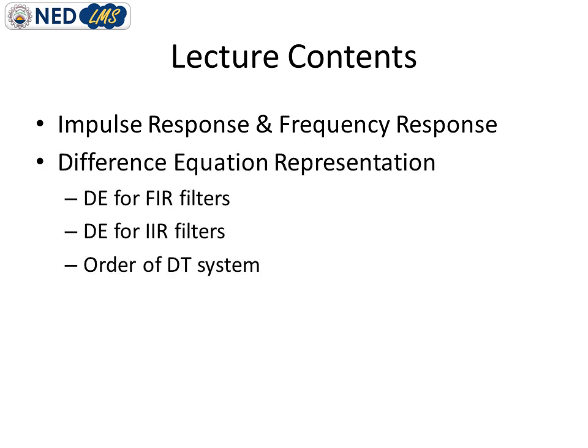After that, we will discuss the second most important representation in the time domain, which is the difference equation. In this topic, I will discuss the standard or generic representation of the difference equation. Then I will discuss the representation of the difference equation for FIR filters, and then the difference equation representation for IIR filters, and what the difference is between the two representations.